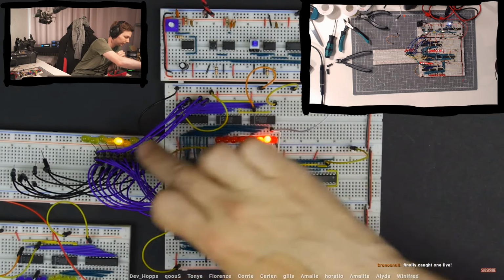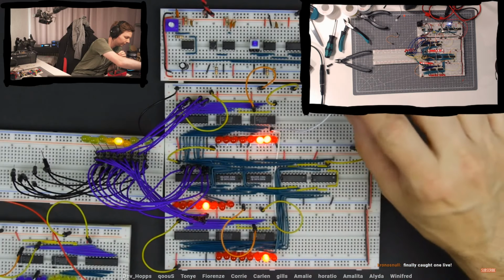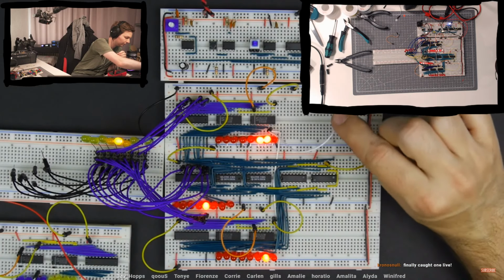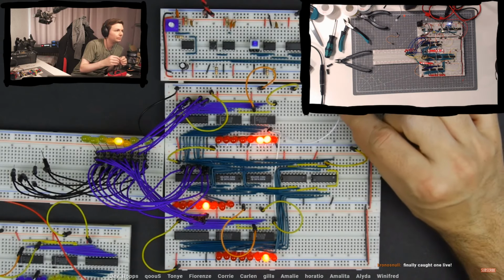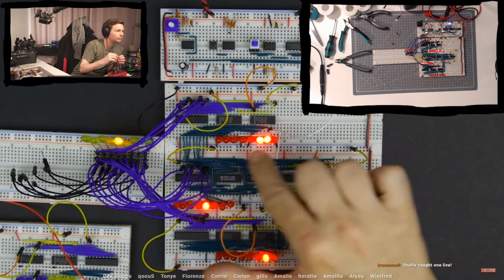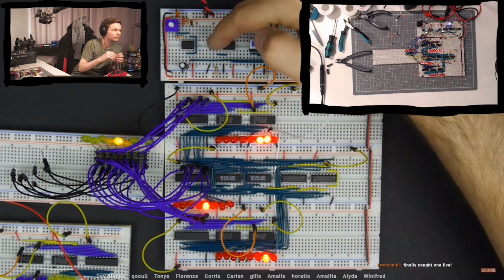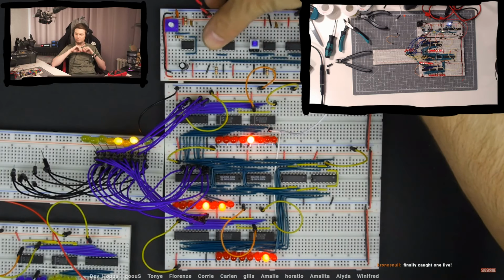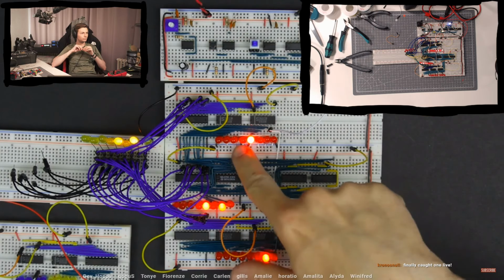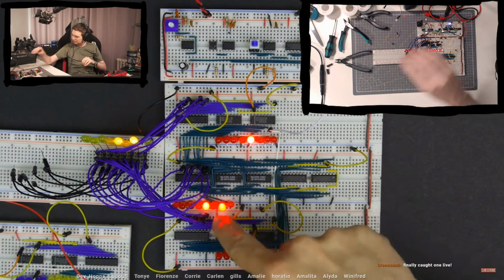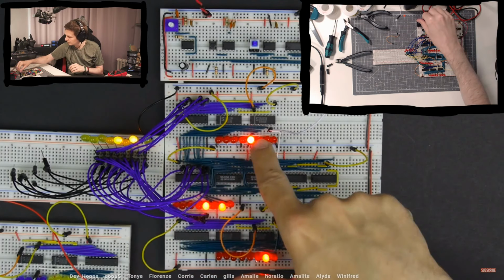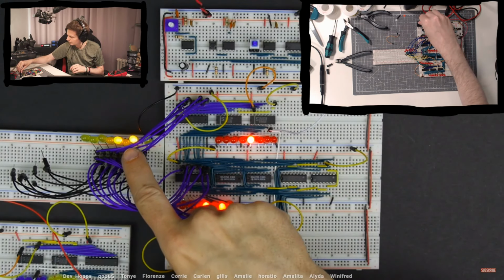So then you would think that the A register is going to read it in again. But because we have the clock, and this is the importance of having that clock in there, it's only going to read just that instant at the rising edge of the clock. So when I push this clock, you see just at the rising edge, it just reads in the 8, and it doesn't then continue to read in the 10, even though this changed almost instantaneously.